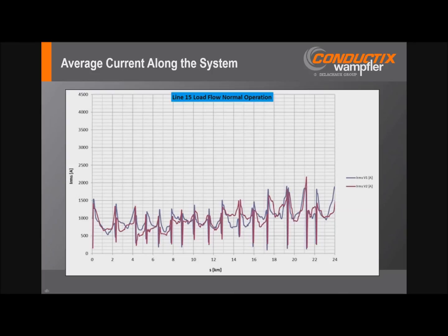So I'd have to get into specifics in terms of what size power rail, what the system configuration is. But general rule of thumb, I know on LRT systems, these have been up to 50, 60, 70 kilometers per hour. You will get some electrical erosion because of arcing, as you saw in the photo, but I'd say that's probably pretty safe.